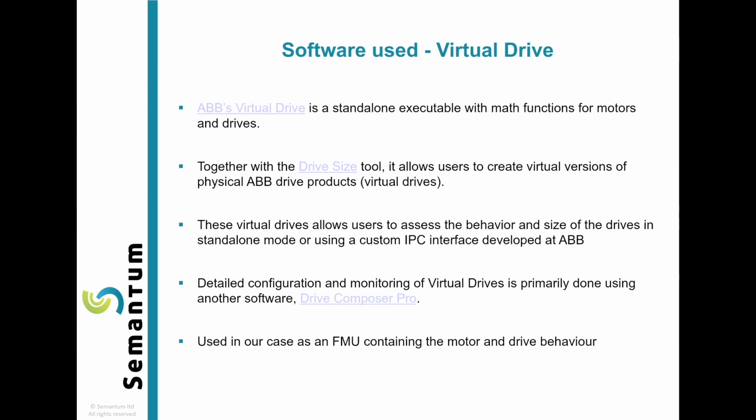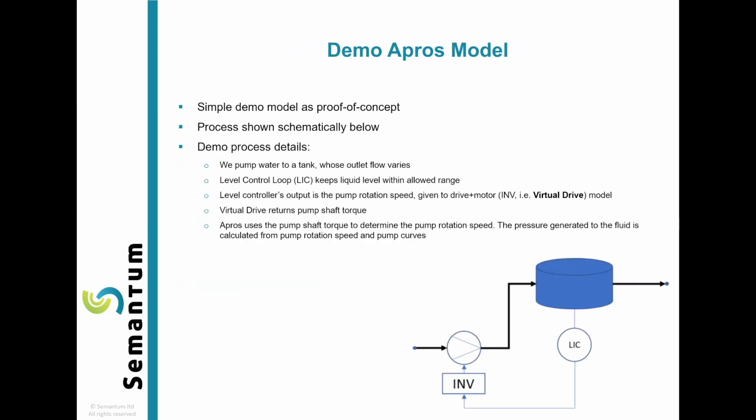And these virtual drives allow users to assess the behavior and check different sizes of drives in standalone mode or using a custom inter-process communication interface developed at ABB. And generally speaking, when people use Virtual Drive and configure it, they use a software called Drive Composer Pro to configure it and monitor it. And that's the primary workflow of using it. And in our case, we implemented an FMU version of this virtual drive containing the motor and drive behavior.